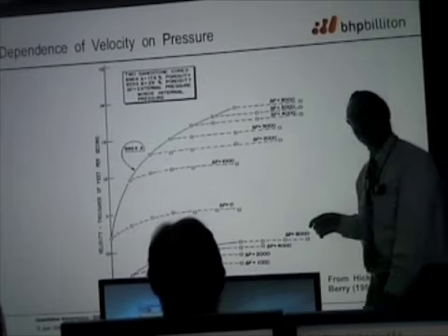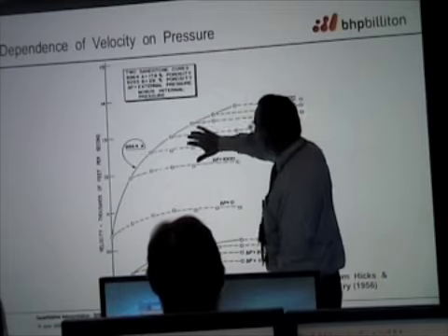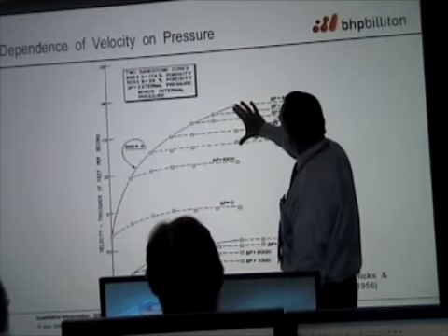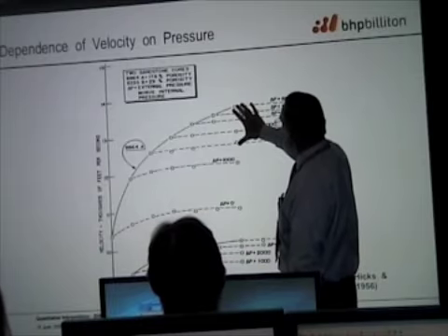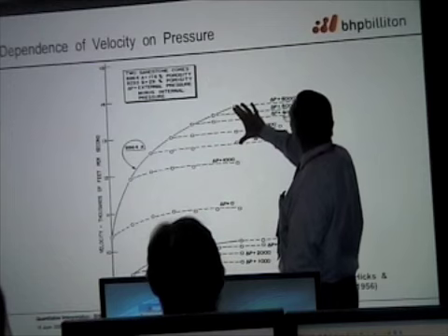We'll say it again for the camera. Yes. But if you're up here, just notice that the curve flattens out. And so if you release the pore fluid pressure, as you do when you suck on the well and try to produce your fluids, up here you don't get near as big an effect for the same amount of change in pore fluid pressure.